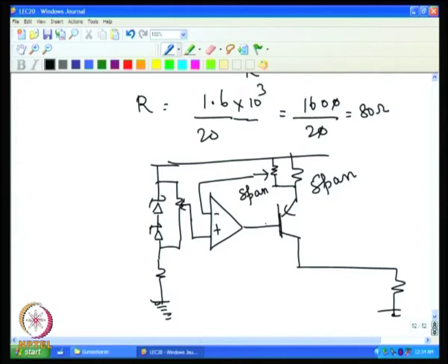Of course, we also have to add a Darlington here to make sure that whatever current is flowing, the same current is flowing here, and we want to make this base current negligible, then only the current that is coming here is same as this, because we are sensing this current and this current is taken as output current. So, whatever current that is flowing into the IC will be lost. So, we have to make sure that this base current is negligible.